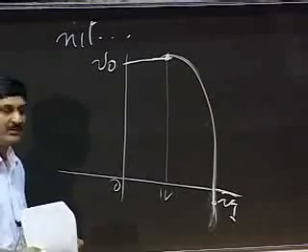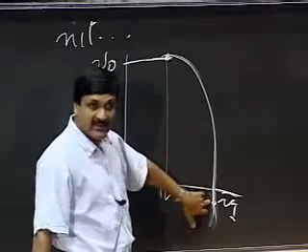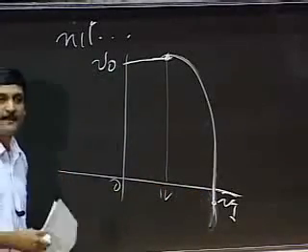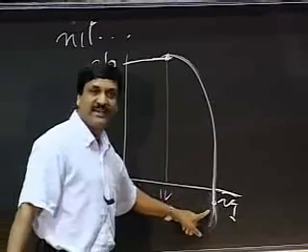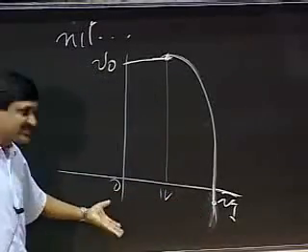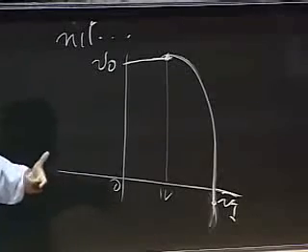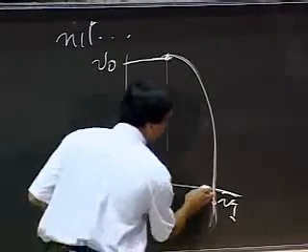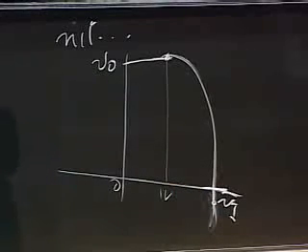Here, on the other hand, my output has gone negative, but it's still sinking current. Because V0 is negative but my current is still in the same direction, the device has now begun to supply power.